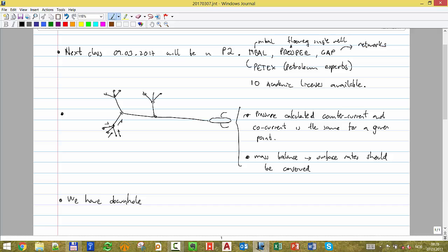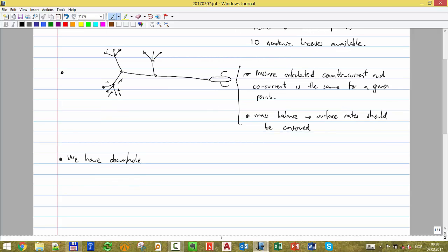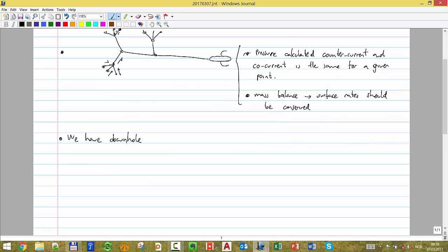So it's going to be important for you to capture this interdependency between the elements of the system. If I make any change in this well, you might think, well, it's 10 kilometers away, it's not going to make much difference, but it's going to have some impact. Important or not, you have to run the simulation to see. If you have a control element, remember you can fix the rate, but then you have to find what is the delta P that you need to breach the pressure.